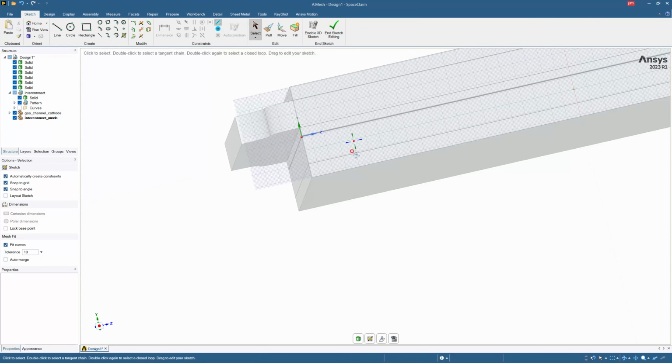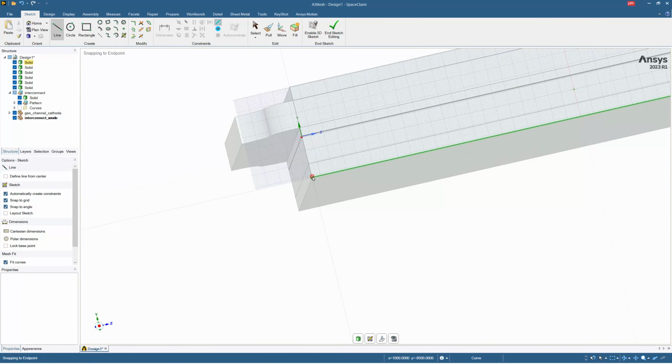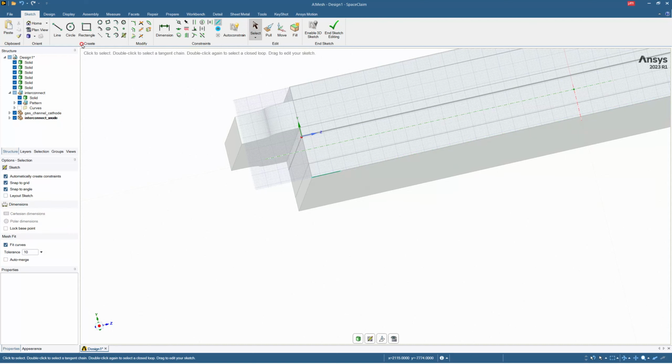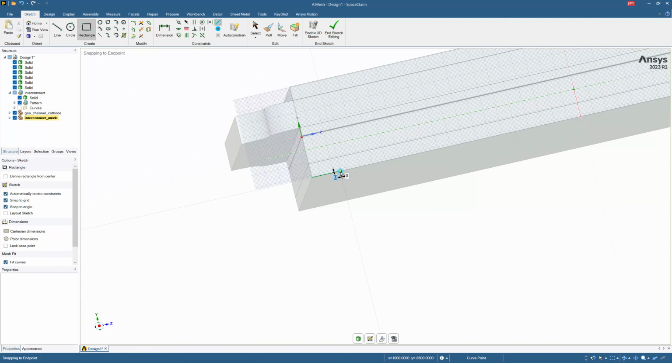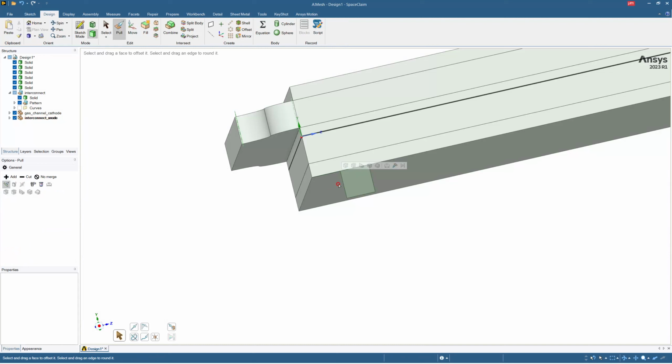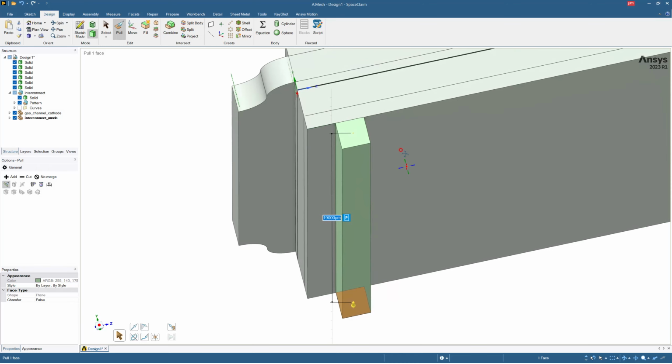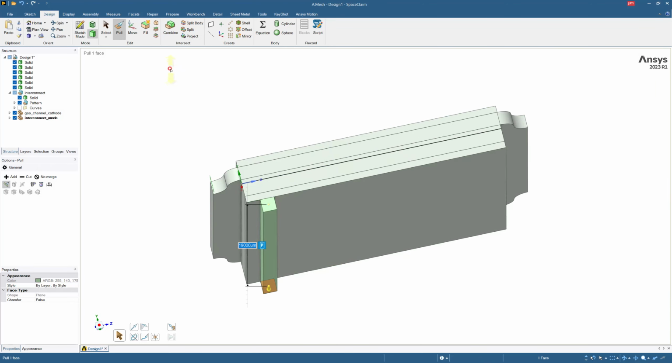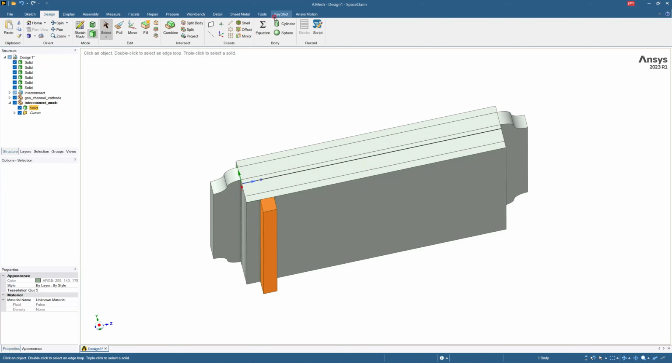But in the interconnect, again, we need to leave space for the gas channel. That will be 1000 micron, and then starting from here we will draw the interconnect rectangle. This is correct.